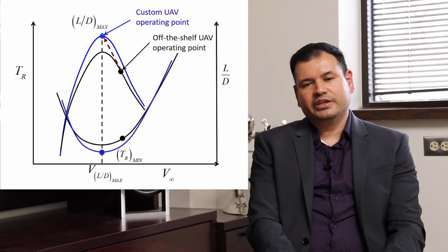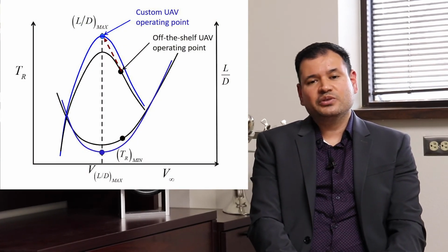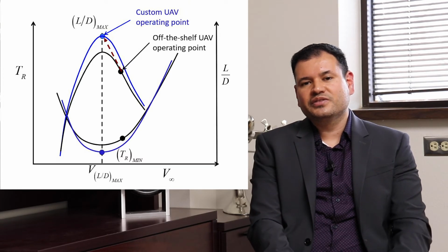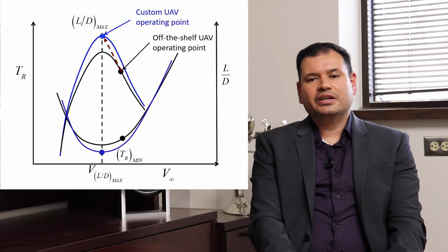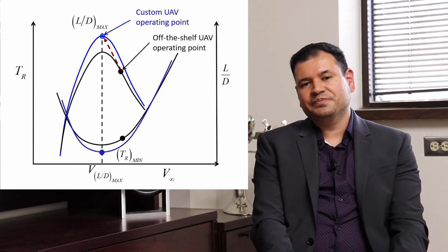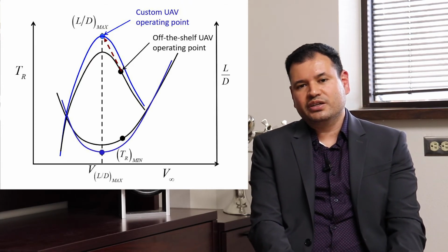Using a combination of these methods, we're able to fly at what we call the aircraft's maximum lift-to-drag ratio. If you take a look at this curve I'm showing here, you have the lift-to-drag ratio, which is the lift coefficient over the drag coefficient. For any aircraft, you want to maximize the L/D because this translates into higher range.